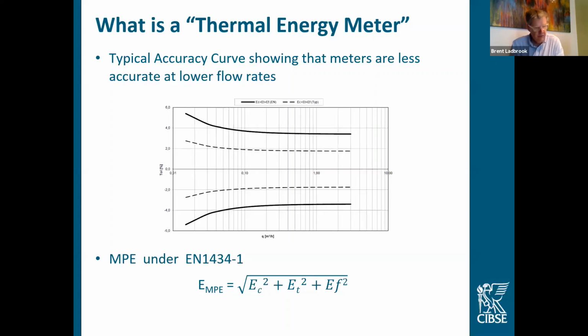And they're opening themselves up to a huge amount of errors. I've even seen people buy an NMI approved water meter and then some temperature probes from somewhere, then write the code themselves and say, well, now my thermal energy meter is NMI approved, and it simply doesn't work that way. So everything adds up equally to our maximum error.